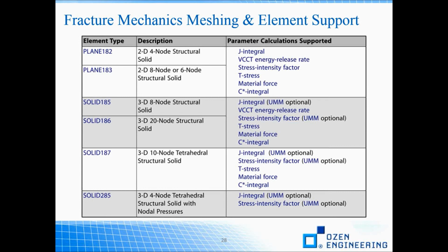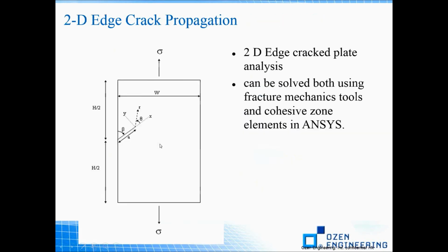There wasn't such a guide with the previous version, but it's a new guide which you can find either as a PDF version or in ANSYS help of release number 16. And most fracture calculations rely on the element nodal connectivity order and must conform to the pattern specific to each element. CINT and KCALC commands are the two important commands to define fracture mechanics parameter calculations.